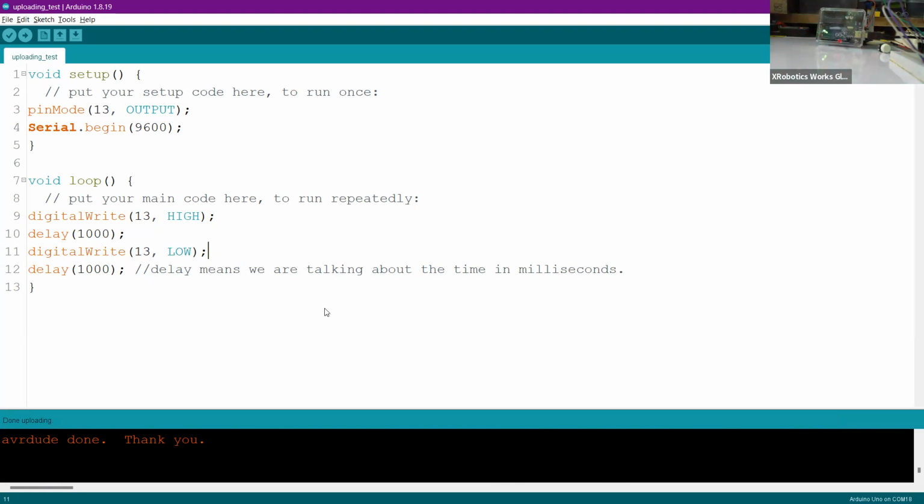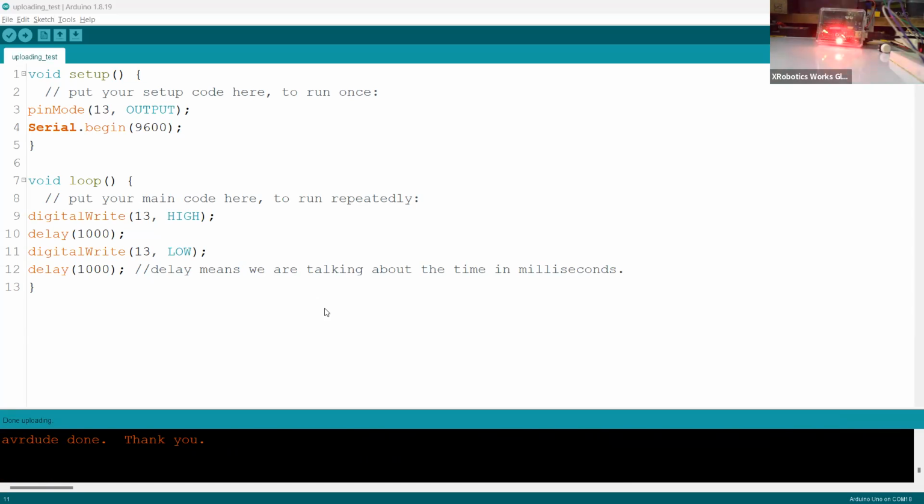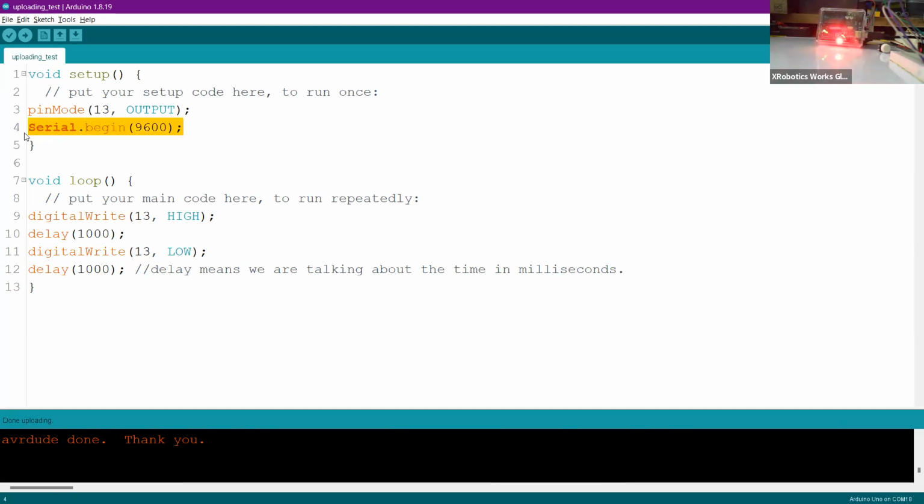So let me head back to the LMS portal. Okay, but before heading to the LMS portal, let me write down the things necessary for the serial communication. So I wrote the Serial.begin function, to help the computer stabilize the communication with my microcontroller at 9600 bits per second. That is the communication speed with my computer.